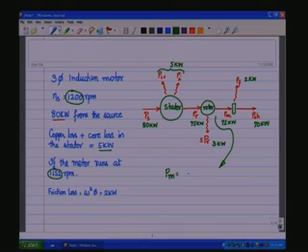Now PM is 1 minus S into PR, PR minus SPR. PR minus SPR, that is 72 kilowatts.